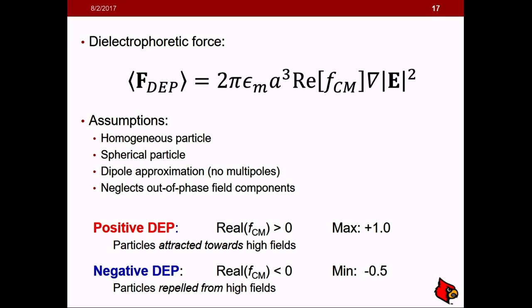So the dielectrophoretic force is inherently significantly non-uniform for a lot of geometries, and we'll show an example of this when we do some introduction to numerical simulations later. So with that, all of these terms that I've gone over so far are positive, except now that deviation, that frequency-dependent variation, there is your Clausius-Mossotti factor.